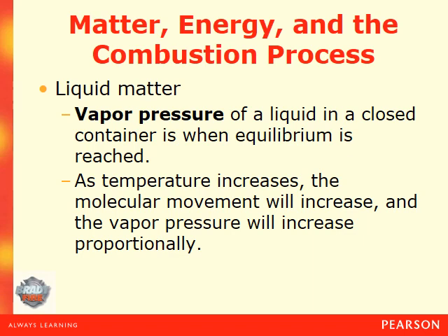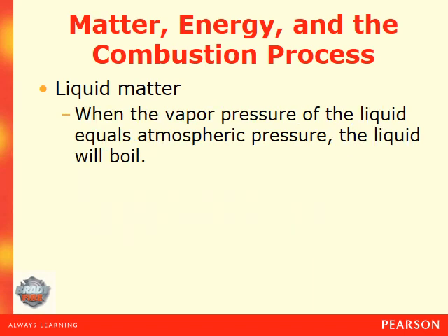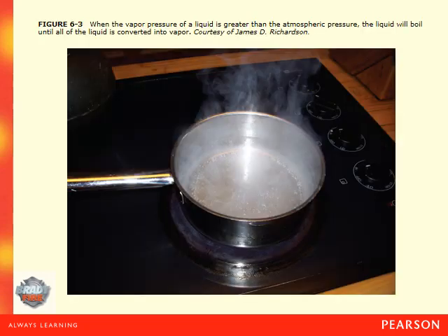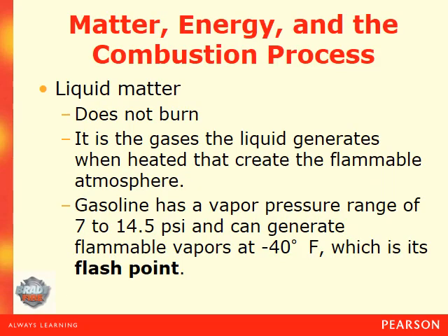The ends begin to blow out or bubble out because of that increase in pressure, and that is vapor pressure, until either the can ruptures or the temperature goes down and that gas starts turning back into a liquid. So when the vapor pressure of the liquid equals atmospheric pressure, the liquid will boil. And it will continue to boil until all the liquid is converted into that vapor or gas.